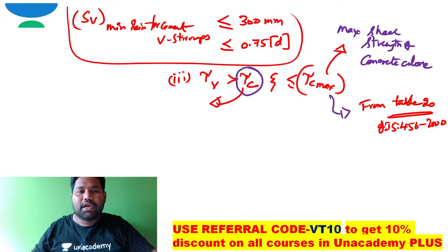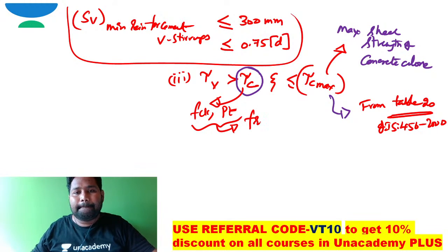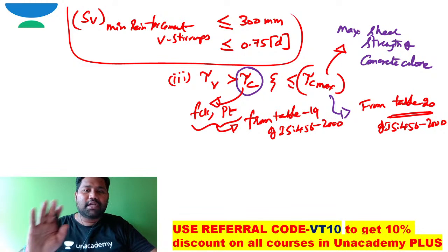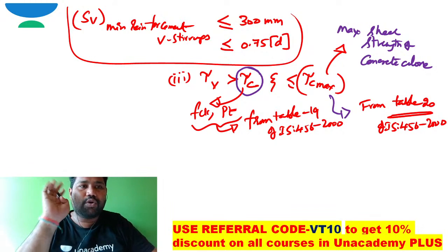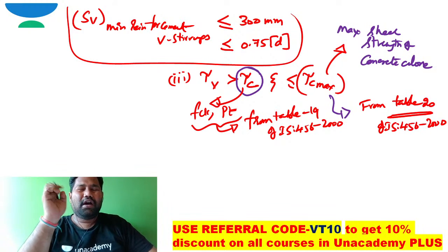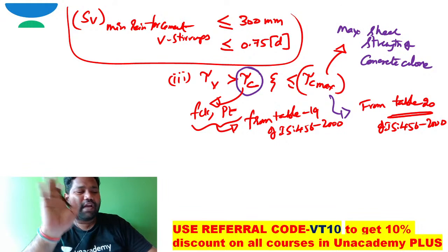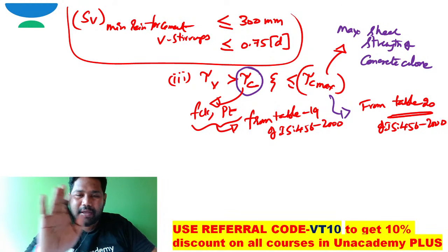And tau c is a function of fck and the percentage of tension steel. You can work out this tau c from Table 19 of IS 456. For your competitive examinations, don't worry, they will give this value because the code of practice is not supplied. So generally this data will be given. Don't worry, there is no need to mug up anything.